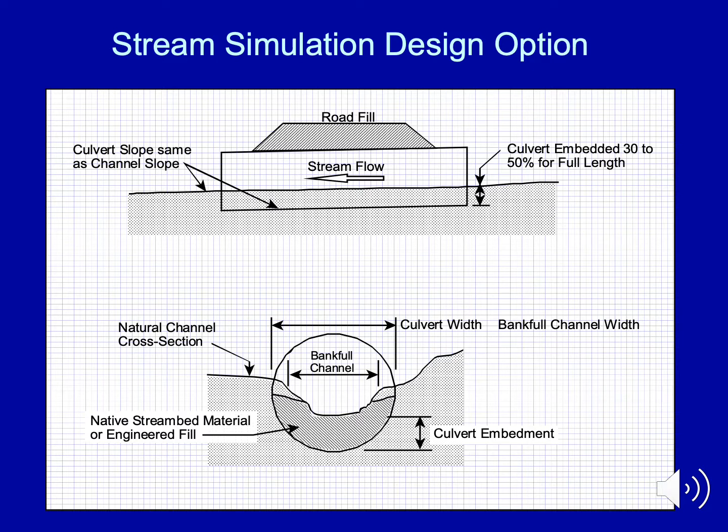A key component to getting this crossing right is finding a reference reach. In almost all cases, you're looking at something upstream and collecting very detailed information of your reference reach to understand the channel morphology, shape, what kind of forcing mechanisms are working upstream, and replicating them within your crossing.